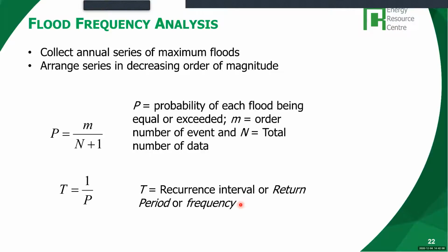For example, if you have 30 years of data, the highest flood is recorded once in 30 years, so we call it a once in 30-year flood. So this is the basic idea. I will show you the example and also send it by email. I will send it again for anybody who did not receive it.